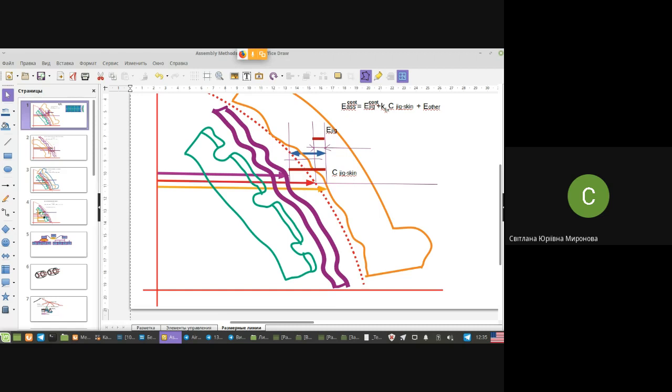So when we are attaching skins to locators, we not only increase the accuracy of these panels, of these aggregates, and as a result of the unit and of the panel, of the aggregate, I mean the whole fuselage, but we also increase interchangeability of them. Well, let's come back to calculation.